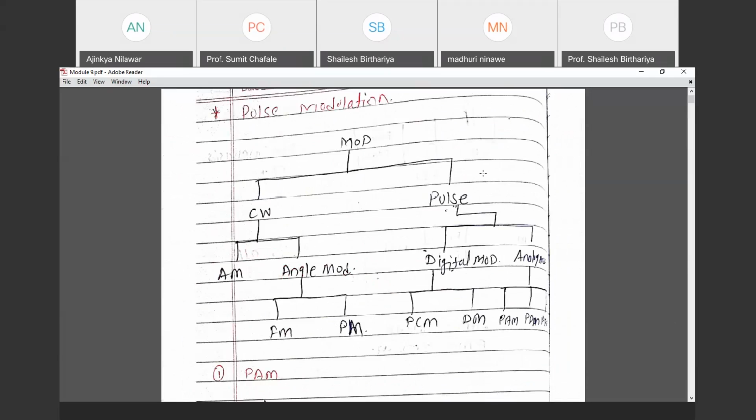As far as PCM is concerned, if you are having any doubt, let me ask. I will brief what exactly we have covered. In the first discussion, we have covered all the digital modulation techniques: PCM, DPCM, then delta modulation and adaptive delta modulation. What happened in PCM? The encoding block depends on the value of n, the number of bits generated. If more bits, then more bandwidth, and more bandwidth means more channel capacity. And for reducing that bandwidth and channel capacity, we are using the DPCM technique.